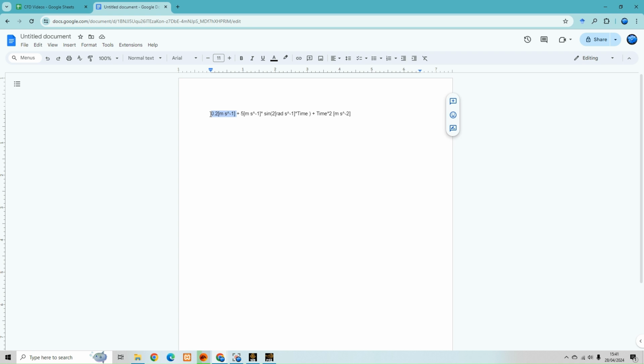What I sometimes find is that when I do crosswind cases where one of the boundary conditions isn't doing anything, there's some numerical issue. I'm not quite sure what it is, but what I'm going to do here is just specify a really low speed wind coming in at the side, shouldn't affect the flow really, and then the main gust will kick in.